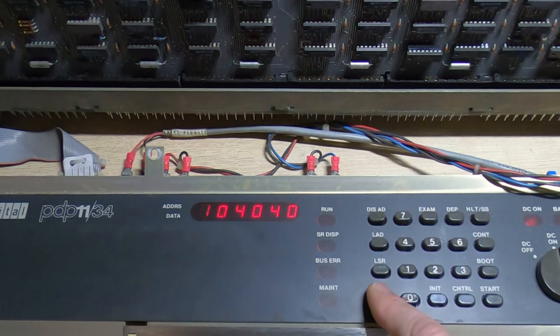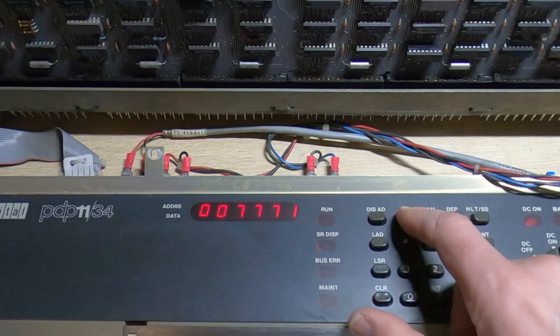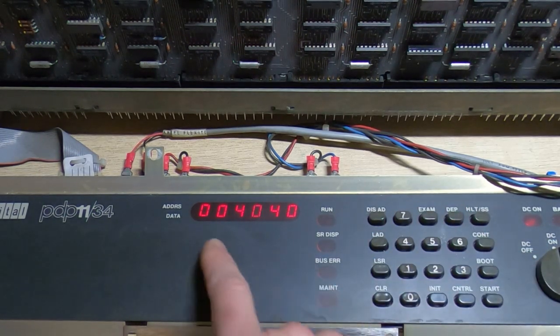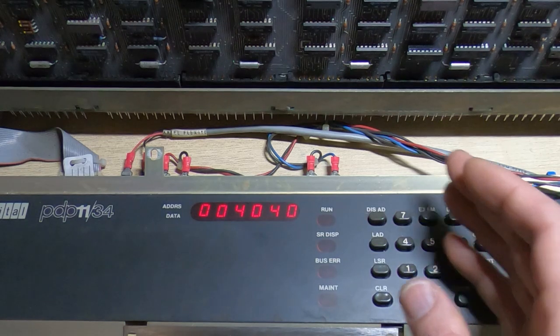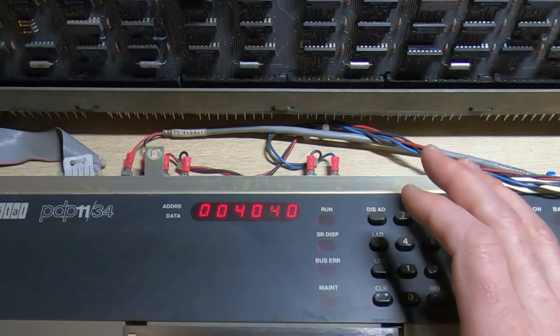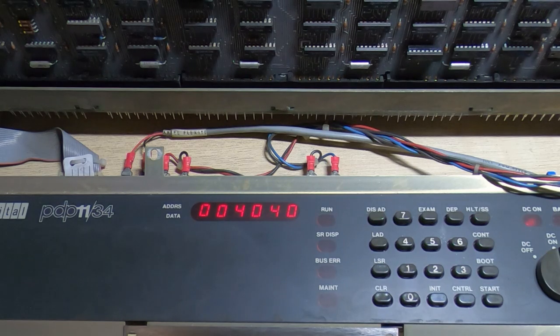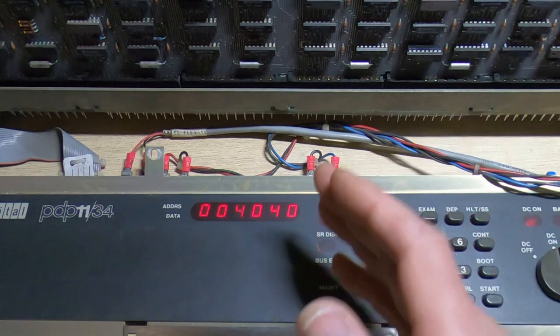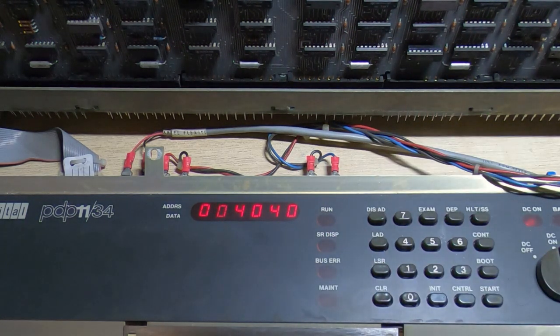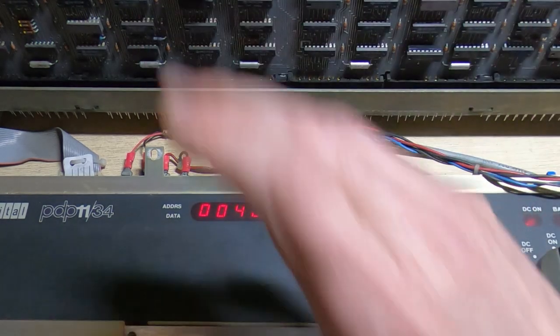So I'm going to try something else. We'll try a lower value, examine it. Notice this time there's no error. So what I'll be doing, I'll do it off camera now. I'm going to start working my way through various values, doing this same thing, driving to different offsets, tracks, sectors, and see where the problem comes in, and if it's at a boundary, so if it's a particular bit being turned on or expected to turn on and it's not, I can then start trying to track that down in the drive control electronics.